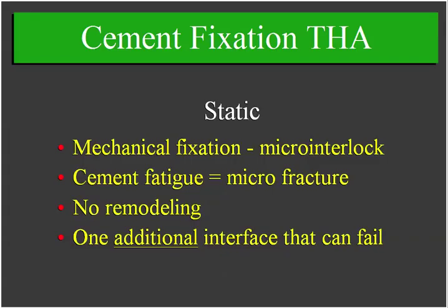Remember that cement fixation is a mechanical fixation. It's a micro interlock into the bone. The cement will fatigue and microfracture. Once it fractures, there is no remodeling of that fracture. It also is one additional interface that can fail. So you have an interface between the prosthesis and the cement, and then you have an interface between the bone and the cement. And both of those two interfaces can fail.